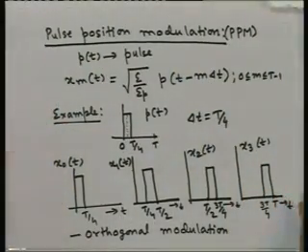Bandwidth can be increased to increase the number of points, while energy and minimum distance can be kept constant, and bandwidth increases proportional to M as M increases. And the number of points M is the same as the dimension of the signal space. So all these properties are true both for FSK and pulse position modulation, PPM in short.